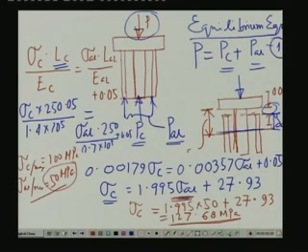That means we will have to limit the stress in the copper rod to 100 MPa and check how much stress it can generate in the aluminum slip, from which we can evaluate the safe load. Hence, if we go the other way, limiting the value of sigma c to 100 MPa, let us see how much we can get the value of sigma aluminum.